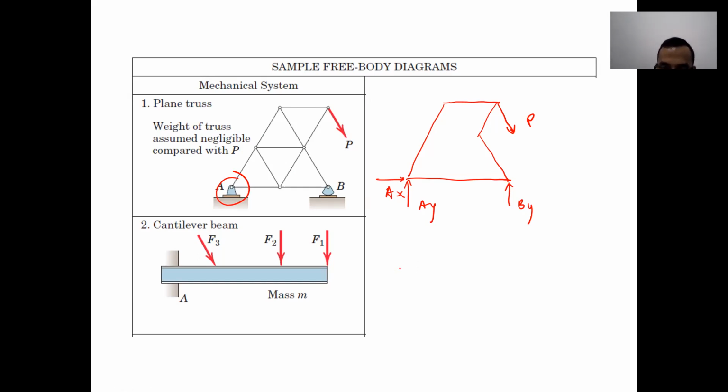First, in the middle, you have to draw the beam, yes, the beam first. Don't forget about that. After drawing the beam, what do you need to draw? F1, F2, yes, and in the middle, another force from the mass, sorry, the weight of the beam. At the center of gravity, COG.